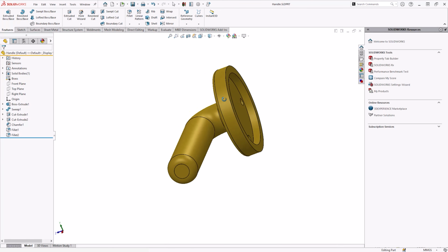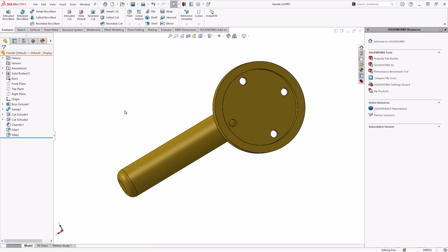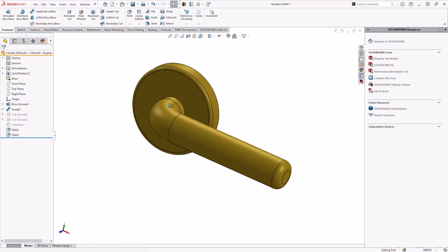If you're exporting geometry from SOLIDWORKS, you can remove hidden and internal geometry. Any geometry that cannot be seen is just unnecessary data that doesn't need to be loaded. You can defeature the model and remove unnecessary detail. How much detail you remove is up to you, but if you're not going to see the component close up, you probably don't need to see all the details down to the fillets and the hardware.